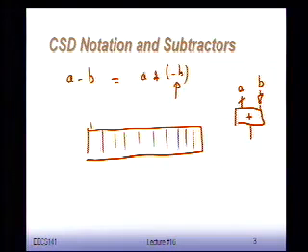So we're already a long way towards our subtraction, but there's one thing missing, right? I have to add 1. So one option is to add another adder, to add a 1 to this thing. This kind of seems to be a lot of work for a very little thing. So any idea how I can modify this little circuit here so that with zero overhead, I can turn this into adding a 1 at the same time as well.